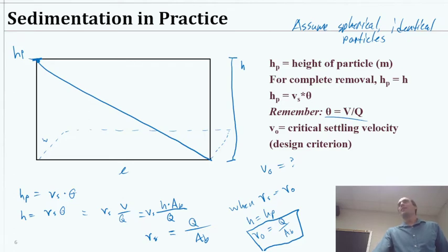So you think, okay, the particle has to fall some height, and so surely the height of the reactor is really important. Well, it turns out it doesn't actually depend on that at all. What matters, in a way it matters, right? What matters is the flow rate through that area. And if you tried to have the same system with a really small height, your flow rate would increase if nothing else changed, right? So your height will affect your flow rate in that sense.